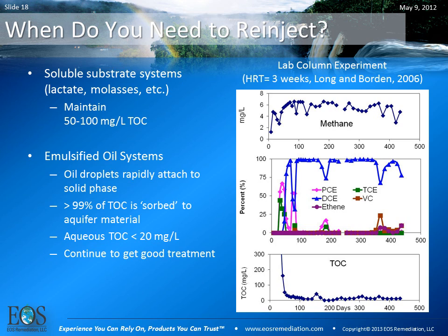If you're using a soluble substrate system like lactate or molasses, typically these get burned up fairly quickly. They ferment fairly quickly, produce a lot of hydrogen initially, and then not a whole lot later on. And so you're going to have no choice but to re-inject a lot sooner than you may want to.